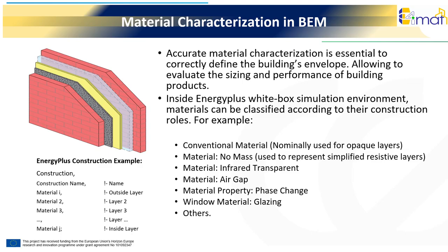energy performance. Through rigorous simulation, especially by the use of a calibrated BEM, materials can be tested virtually under a variety of conditions, exploring different layer combinations, optimizing material thicknesses and position, and thus offering insights that guide product optimization and ensure that real-world performance aligns with expected outcomes.